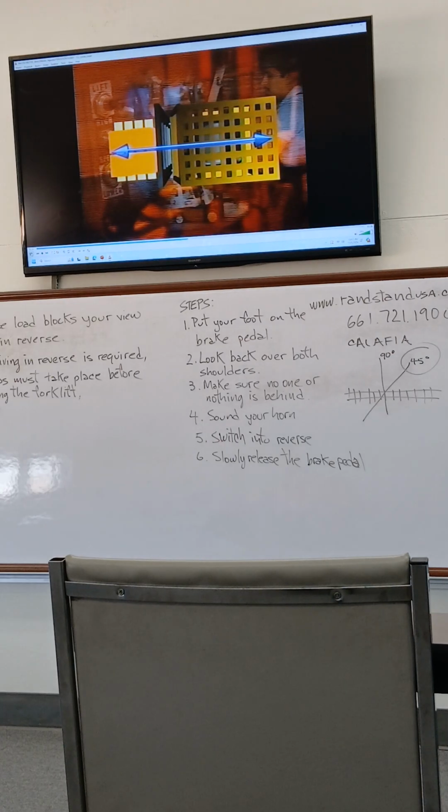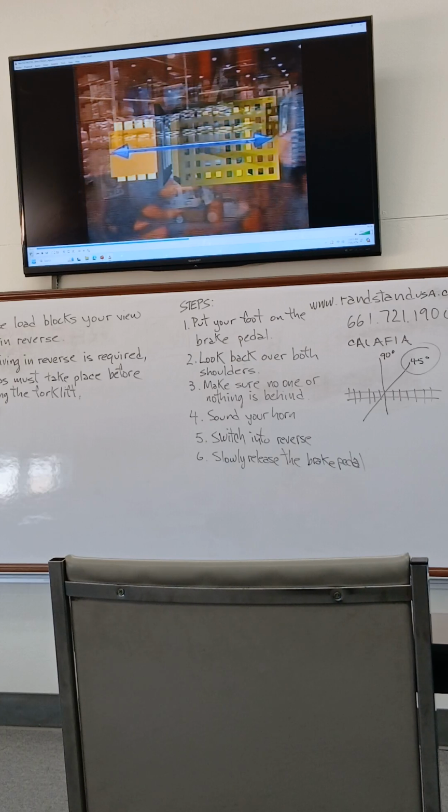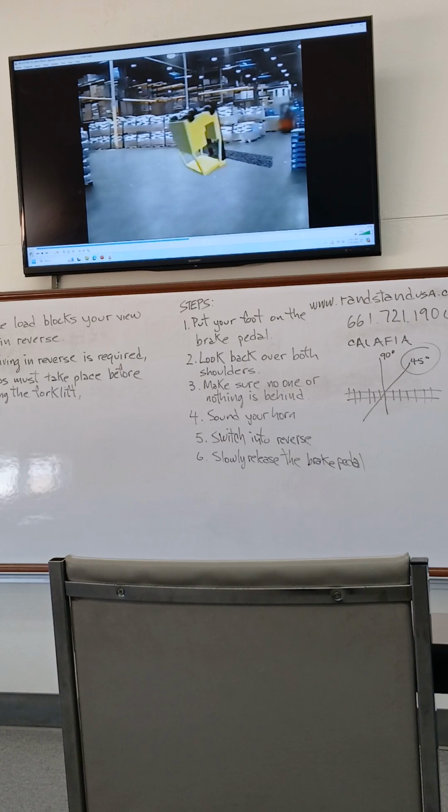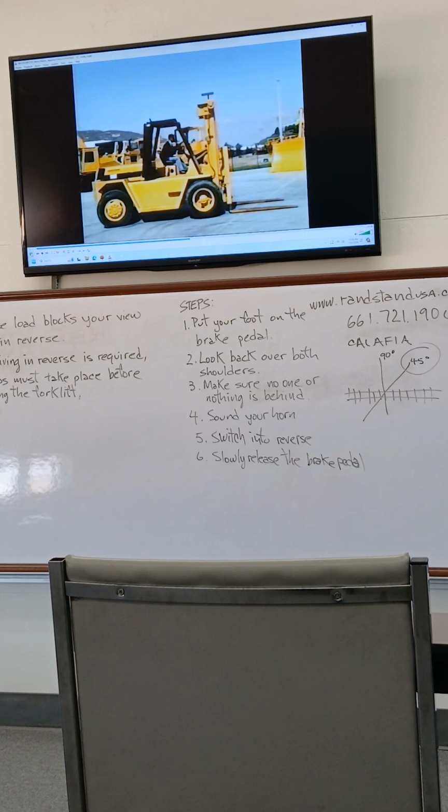A very short forklift would have less longitudinal stability than a very large or long forklift. Let's say you're driving a small, short forklift, and while traveling, you hit a 4-inch curb. Quite possibly, the longitudinal stability of this short forklift may cause you to overturn, whereas a large, long forklift would probably not tip over because it has much greater longitudinal stability.